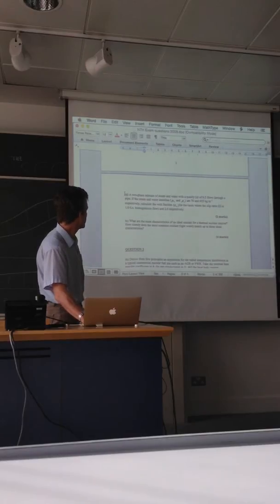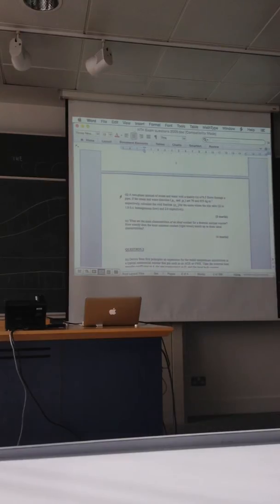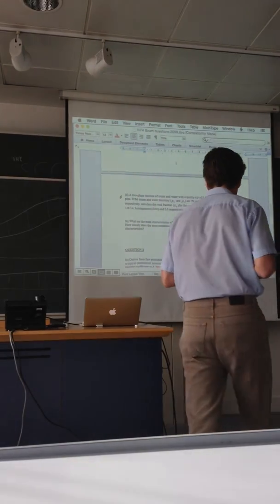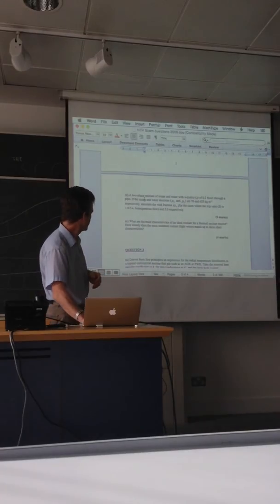That's the kind of thing I started off the morning saying: the basic, simple stuff about the bread and butter terminology, notation and concepts of two-phase flow, and how the ideas of enthalpy and quality are related to whether or not there is slip between the phases. The distinctions between how we define them matter only when there is slip. That's an important basic to be clear about, because it underlies everything you'll need to do about two-phase flow, and maybe eventually using correlations. So that's a typical Jeff one.